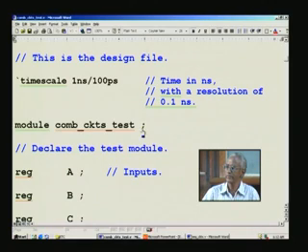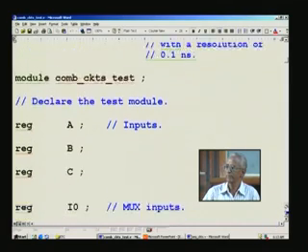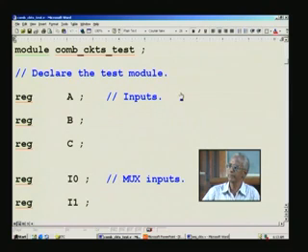And do not forget the semicolon, which tells that the module definition has ended, not that the module has ended. In order to communicate that the module has ended, you have to have an endmodule, which will appear at the very end of this code. Now the difference is that in the design file we declared input and so on, because it appeared right there in the listing, and therefore you will not find any inputs and outputs listed separately here.